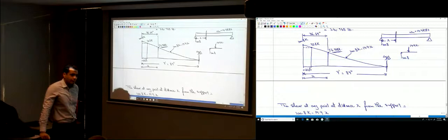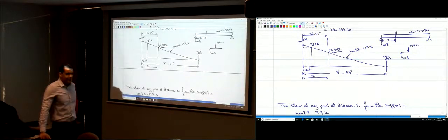Like if we chose 15 inches. You cannot use 15. Why? Because d max, out of those 4 equations, one of them was d divided by 2, which is 11.25. That's the maximum spacing you can provide, 11.25. You just go to the next lowest one.